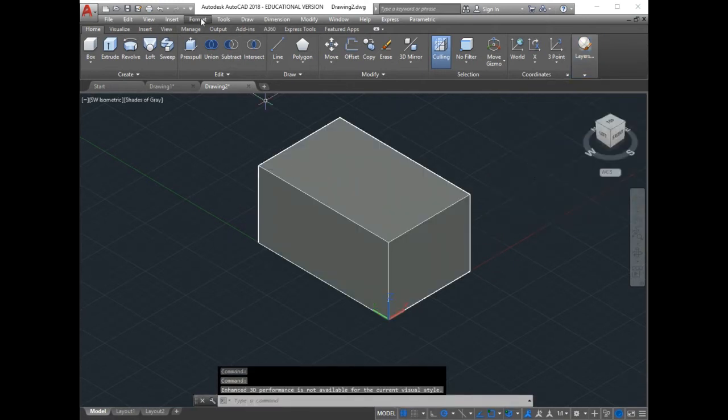And now I'm ready to create a new format for the dimension style. Do we need, guys, to change our dimension style? No, because actually we did not do anything with the limits. So this means that your default dimension style is consistent with your default limits. Remember, usually we go for changing the dimension style in case I changed my limits.